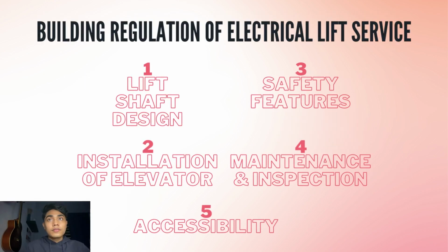So there are 5 building regulations of electrical lift service I want to point out. So first is the lift shaft design. The UBBL lays forth the specifications for lift shaft designs, including their size, structural soundness, and material composition. It makes sure that the lift shafts have enough room for the lift car to move safely and to allow for maintenance access.